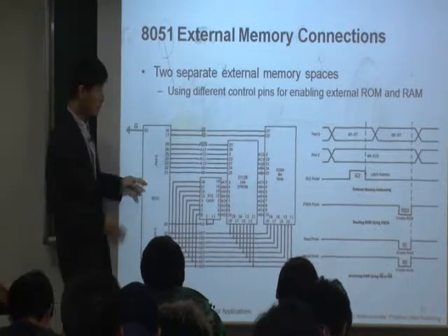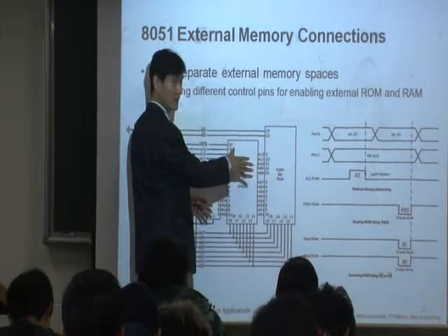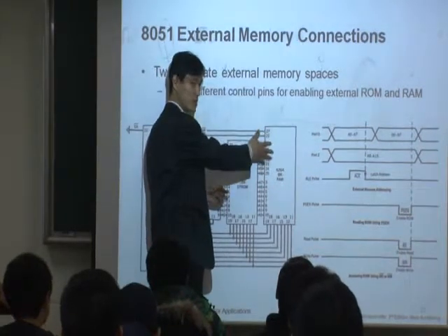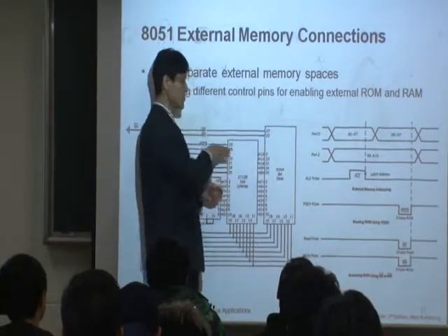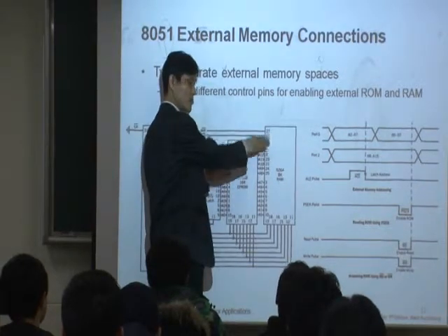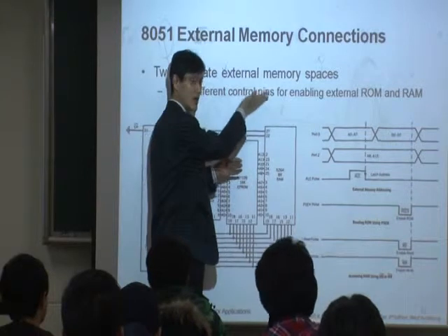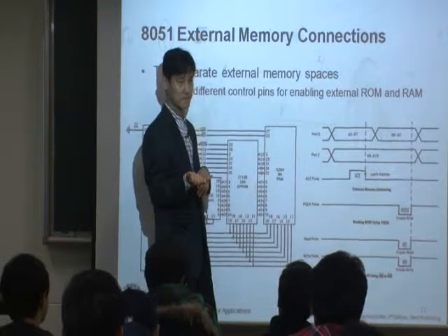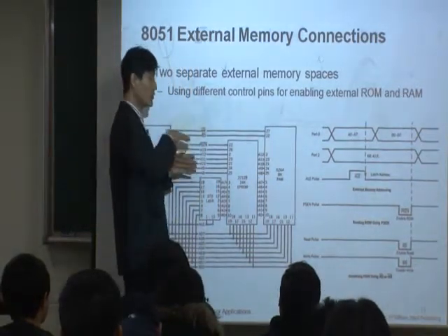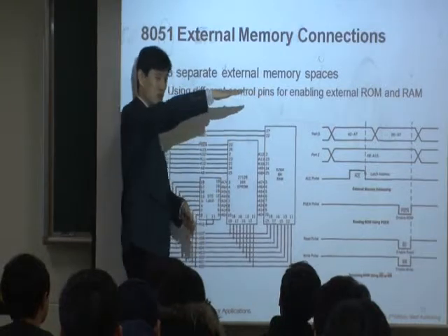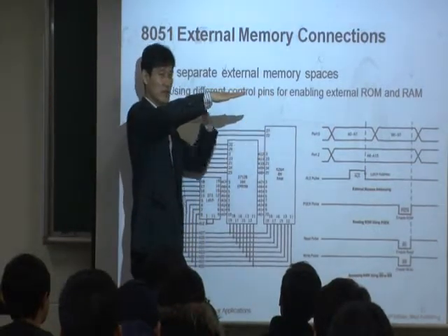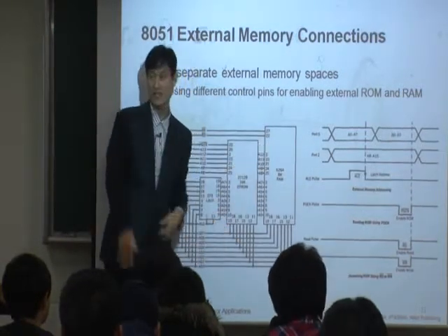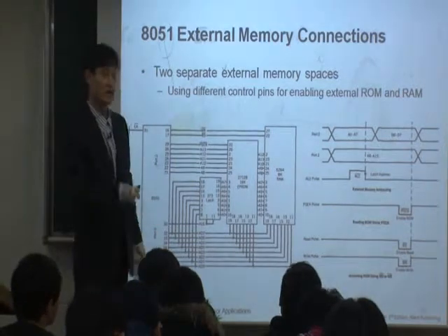Generally, let's say I want to turn on this memory. Then you probably have some signal. Active high means that normally it's a 0, but when you want to turn it on, you put high, or 5 volts, something like that. Then it's active. That's active high. But active low means that normally we give 5 volts, and if I want to turn on the memory, then I make it low. Then it's turned on. That's active low. So when you have a bar, that means active low.